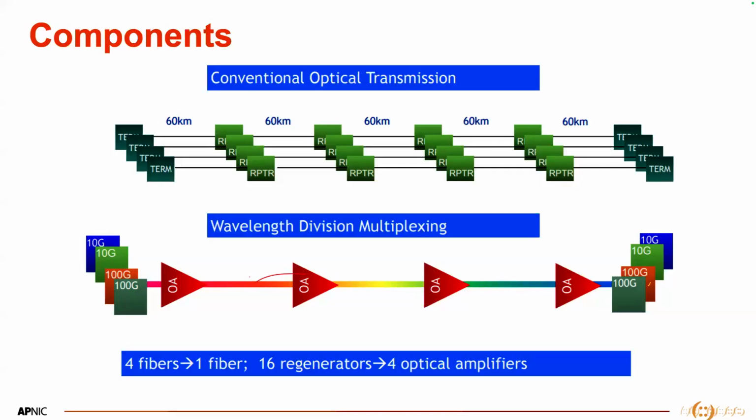You can understand, if you design this network and take this network from that vendor, how much strength you have in your hand. I mean, how strong the OSNR is going to be in your lambda. If you see in the simulation report that the levels are not good enough, you can ask your vendor to redesign. You can ask them to reduce the number of amplifiers in the path, and you can have more discussion with your vendor or with your transmission planning team internally as well.